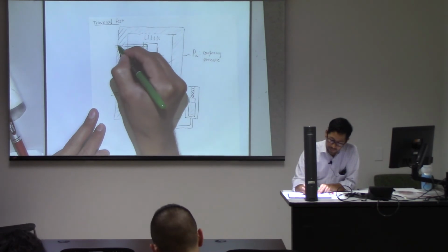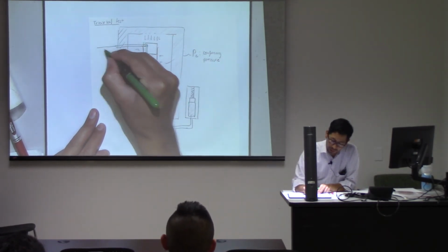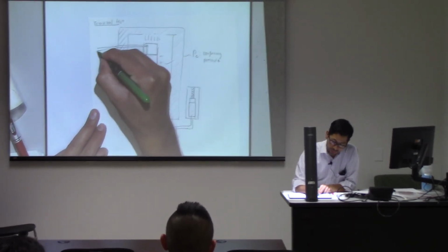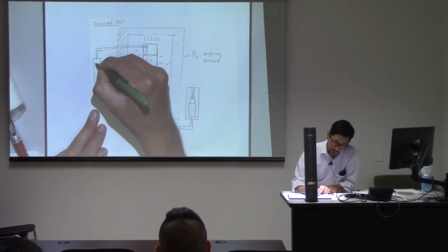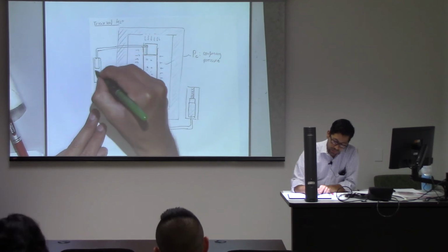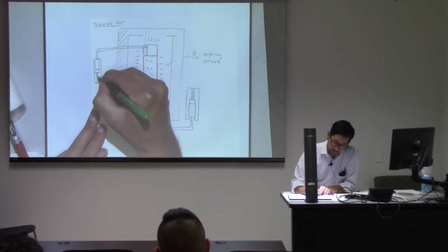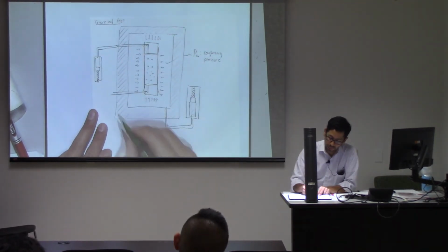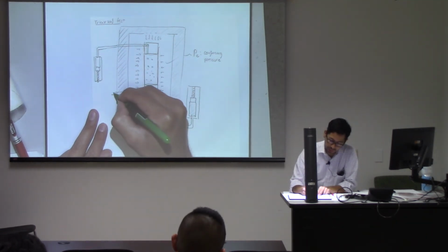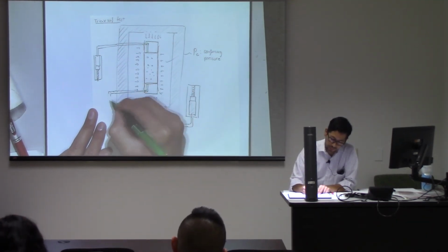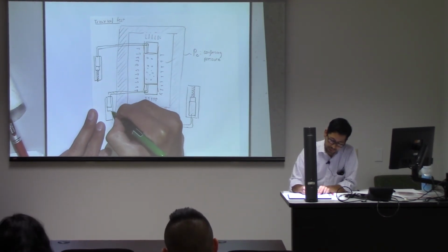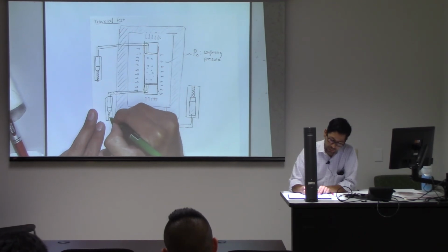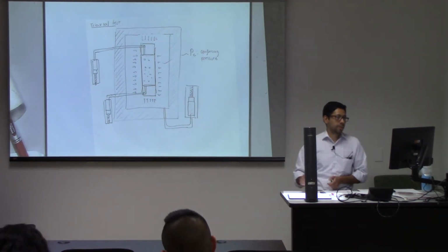and you can connect that to another set of syringe pumps. And what these syringe pumps are going to do is they're going to inject fluids in and out of the sample in order to control the pore pressure and, if you want, to measure permeability.